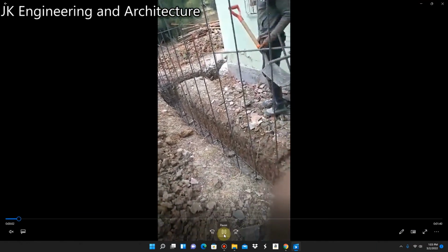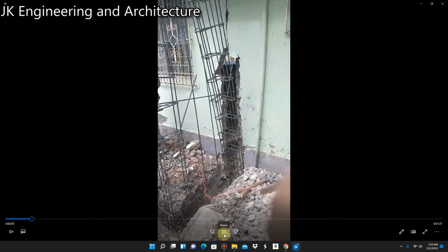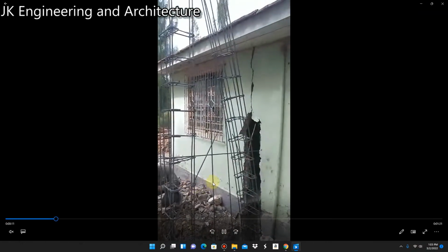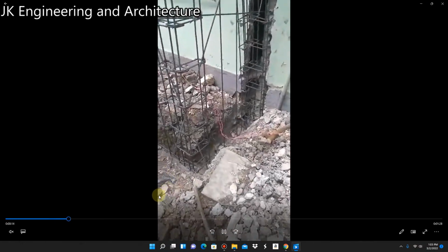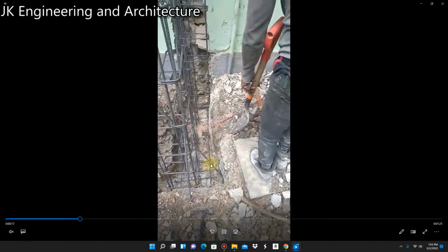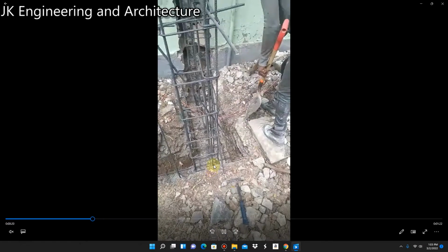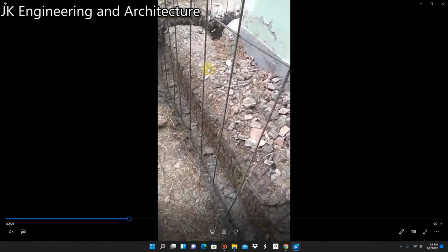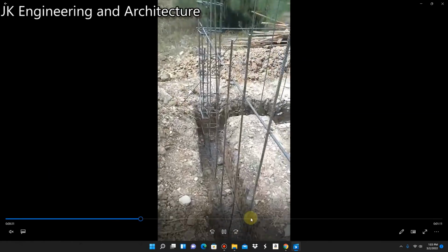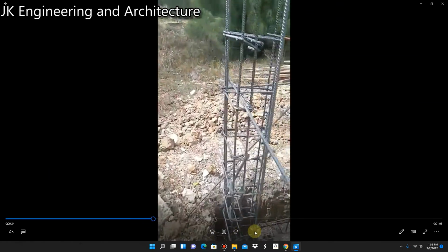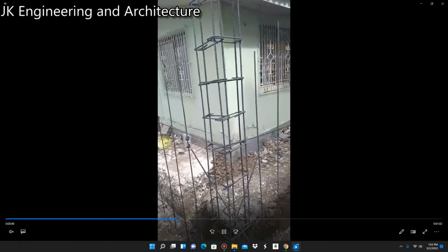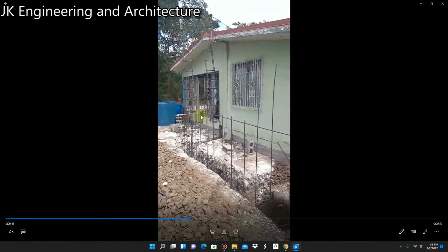So this is another video that I've gotten from the project. This video is showing the reinforcements in the footing. It has finished excavating. We have put in the reinforcement for the foundation. As you can see, we have now opened up that side where we have the shear crack. So we're going to put a brand new stiffener in that corner. As the video comes to the front, we have an L stiffener right here, and we're going to have an L stiffener on the opposite side.